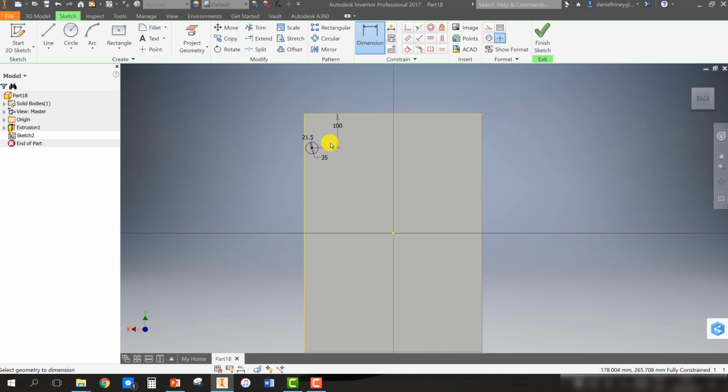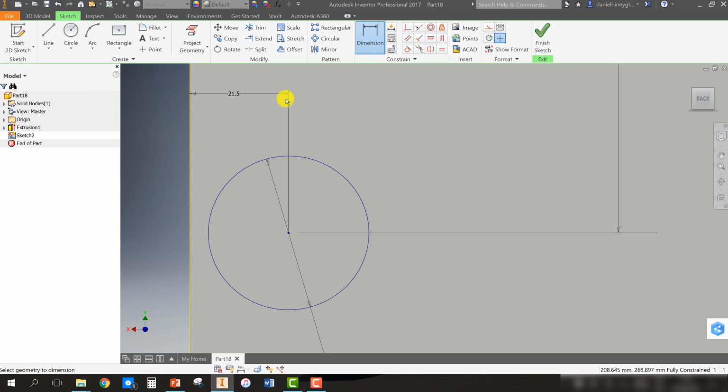Next thing we want to do is create two little holes for your screws. So we'll do two little 3mm holes. So small_diameter, and we're going to let that equal 3mm, and we'll do the same on the far side.